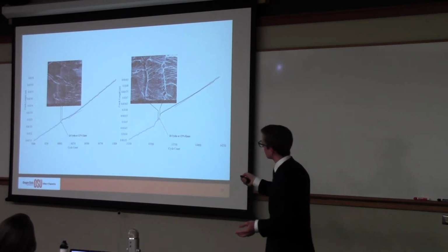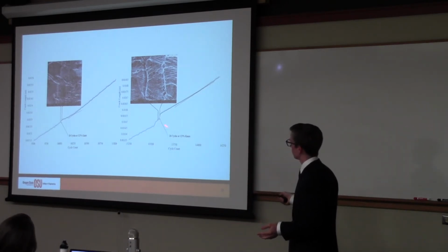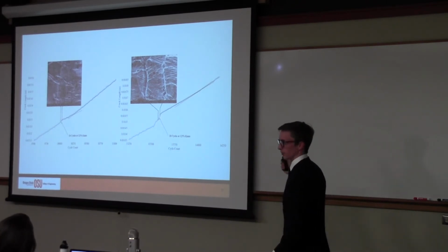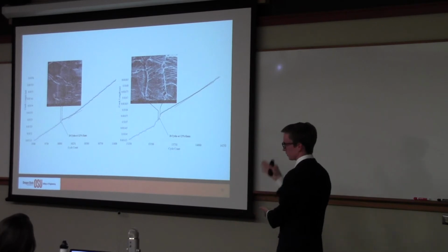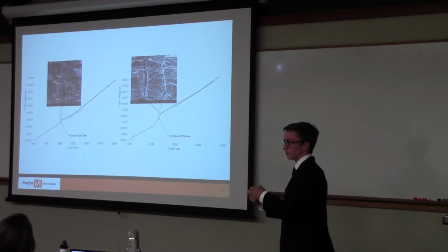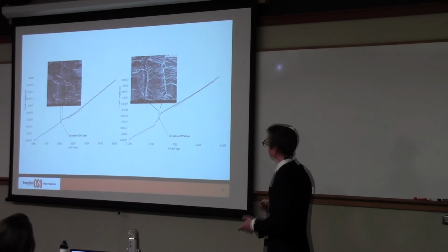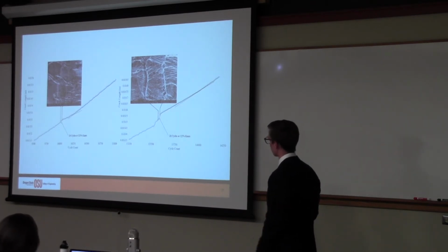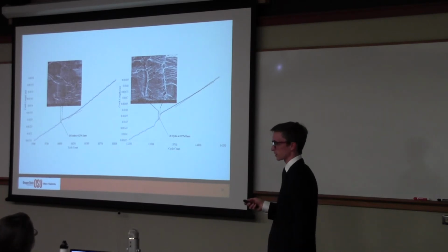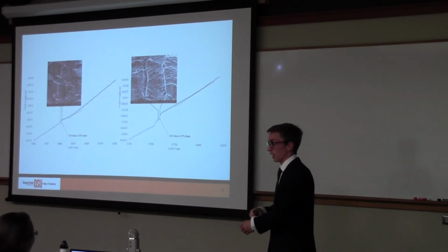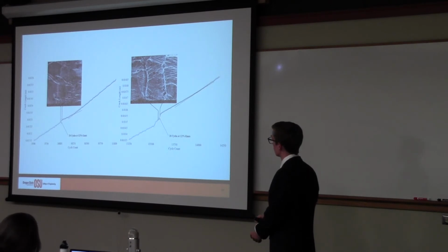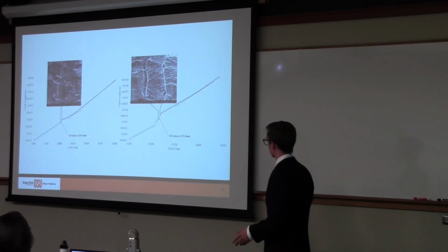But then when you go to a higher stress intensity and you apply an overload, well, first you get the branching behavior. You can see it's branching into the fracture surface. If you were to use your imagination and look at it from the side, you'd see that branching, right? And then you see that at higher stress intensities, is there any discernible retardation effect? I don't think so. These lines pretty much overlap, and it would appear that at those stress intensities, stress relaxation is so high that there's no retardation effect at all.